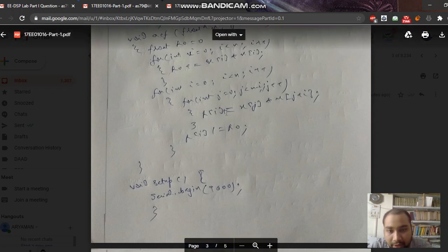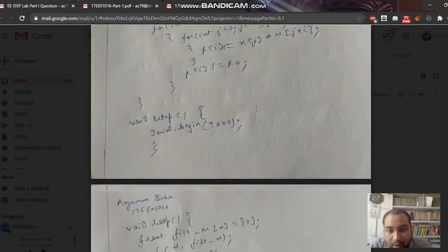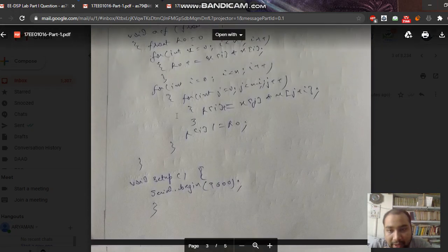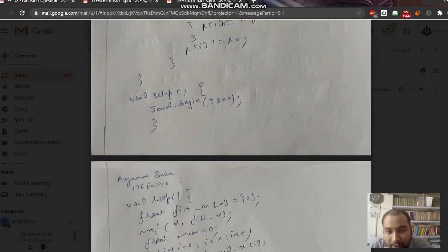The autocorrelation is the shifted multiplication of the original signal, with index j plus i, using a window of n minus i, multiplied with the original signal, and by this we get the normalized autocorrelation function.